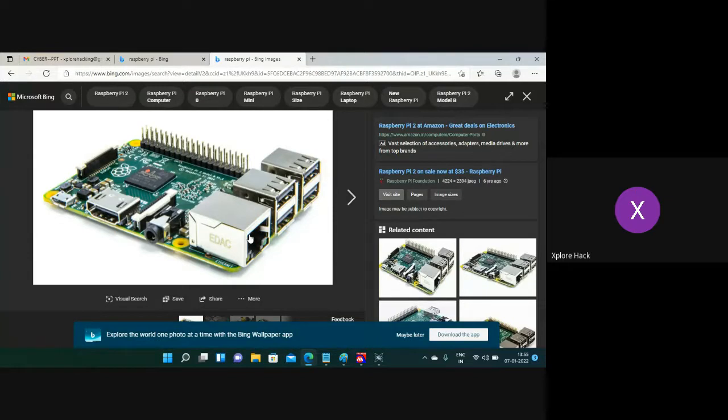And you want to see the output of this Raspberry Pi board, right? To view the output, this Raspberry Pi board is given with an HDMI port. So you need to find a converter from HDMI to VGA if you are viewing the Raspberry Pi board's output on a monitor. You have to find a convert cable.